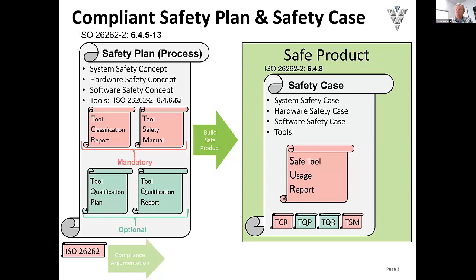Let's say you are a supplier for an OEM and you want to add them some software or safety elements, then you will ship the safety elements to them, but also the safety case. They will ask you for the safety case, and they will look into it and say, oh, where's the code coverage report, or where are other things? You are free to have your own process, but the process has to be compliant. So there has to be a compliance report. You can use different compilers as you like, but every compiler that you use has to be classified.